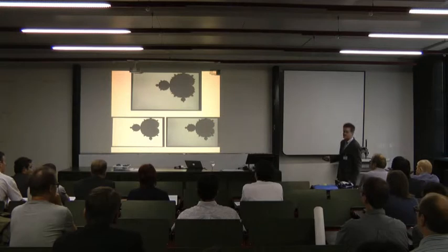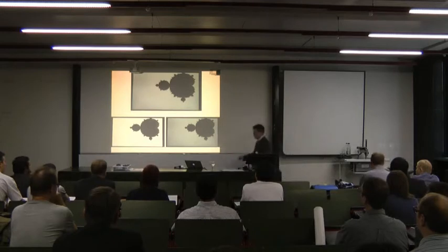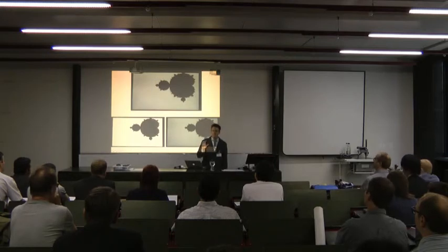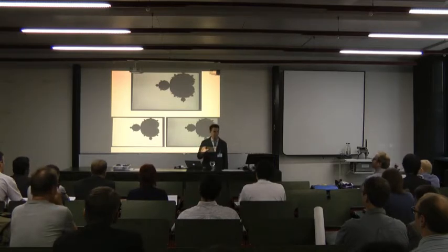And over here we're going to see LegUp pure hardware where we applied loop pipelining. Okay, let's take a look at the video of these three different cases. By the way, the LegUp accelerators are running at less than 200 megahertz. This is actually a beautiful example of how, if you can tailor the hardware circuit to the computations, you can actually get much, much better performance over a processor that even runs multiple X faster.